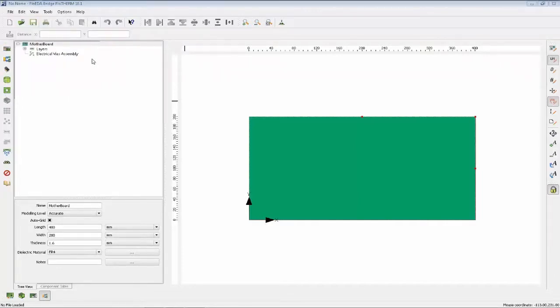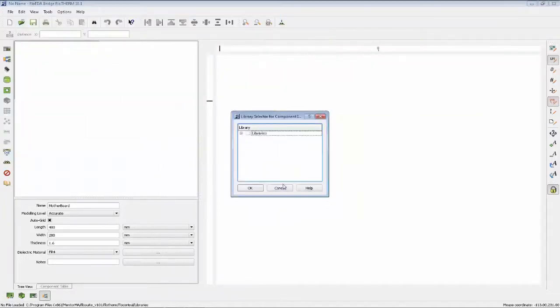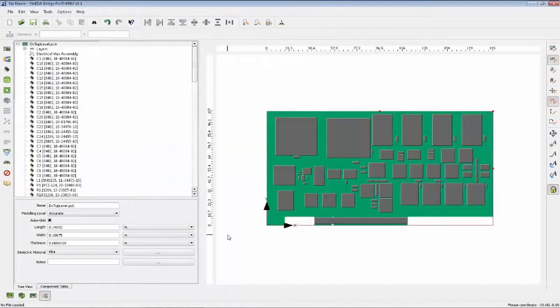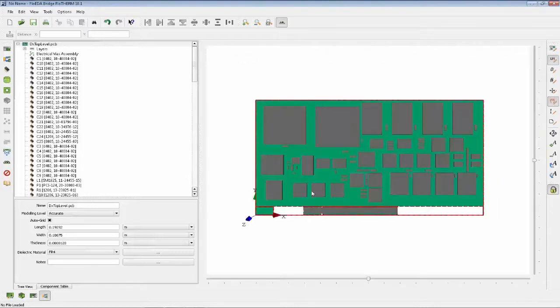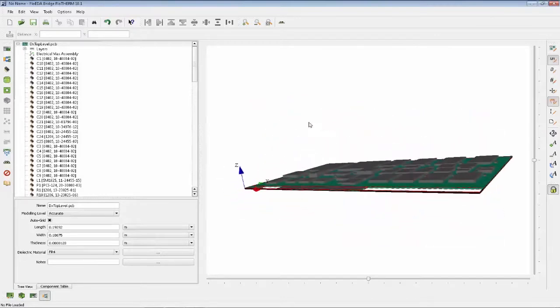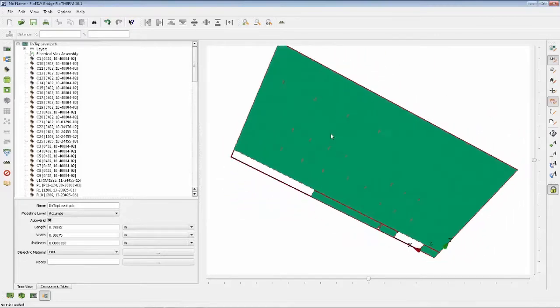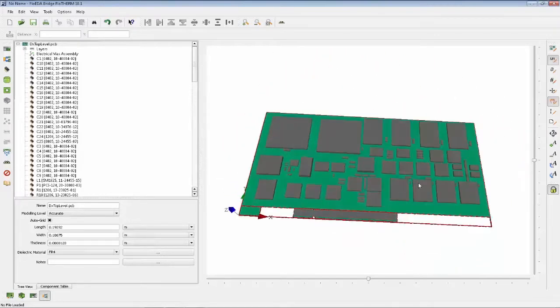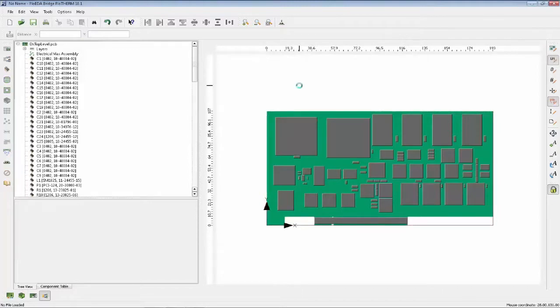So let's just load that into the software. The FloEDA file effectively has the PCB shape, size, cutouts. It also has component shape, size, location, and also height information, which is important. So if I look at this in 3D, like so, I can spin that around, make sure that I've got my PCB with all the components in the correct location. Now let's just change the view back to the top again. So we can start to work on this PCB and add more thermal data.